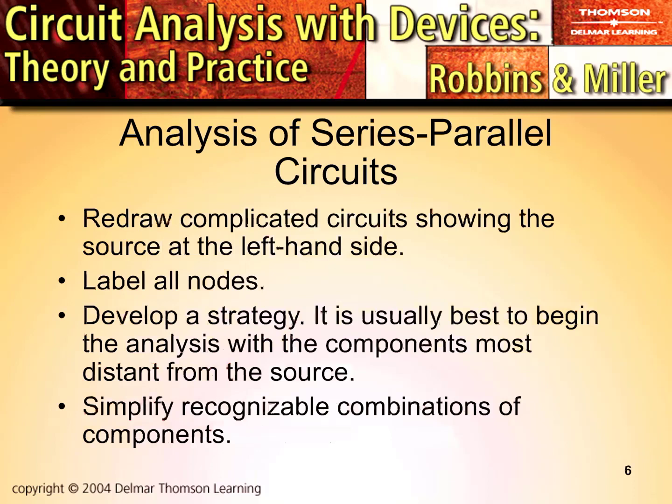Analysis of series parallel circuits. Redraw all these complicated circuits, and we came up with our rules, right? Sources on the left vertically, loads on the right vertically, and label all nodes. Nodes are points of current division. If they haven't been already labeled or given names, give them names before you do a redraw.